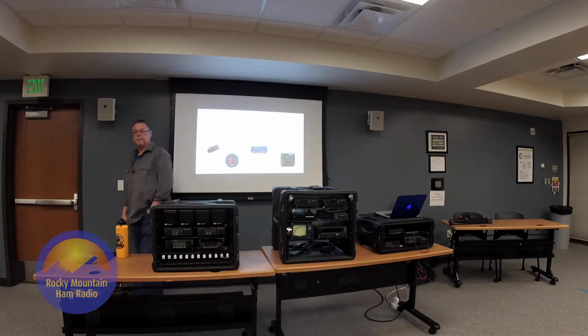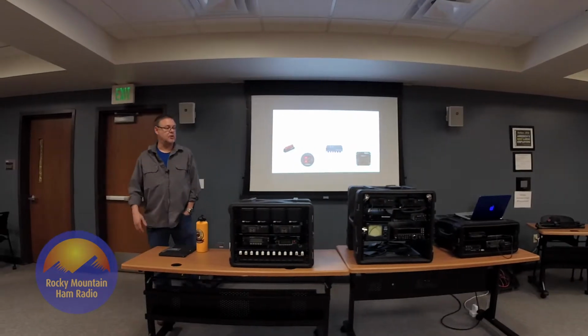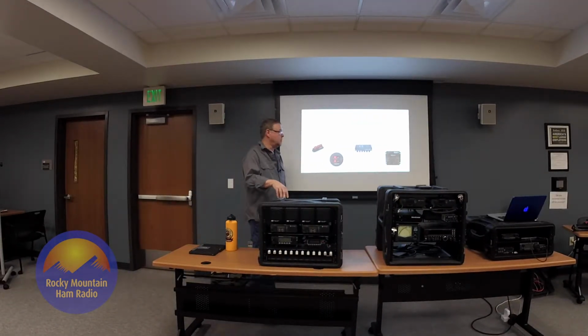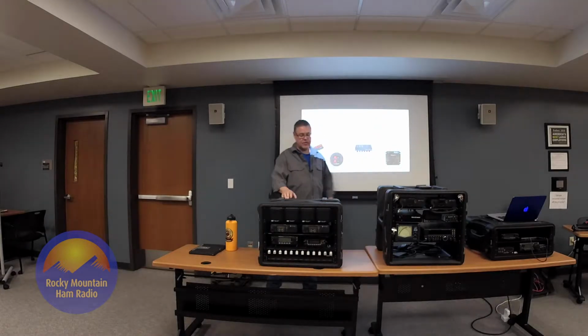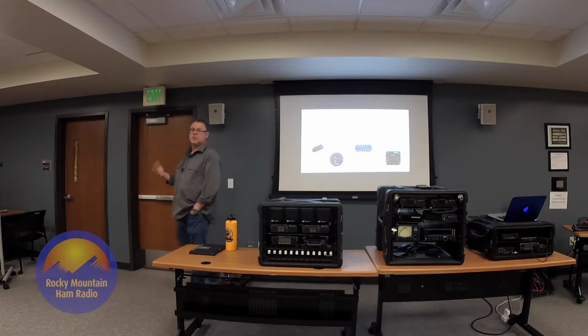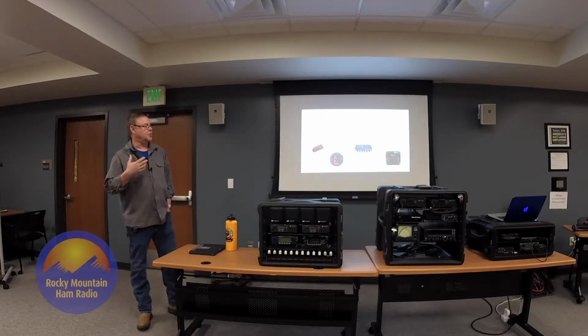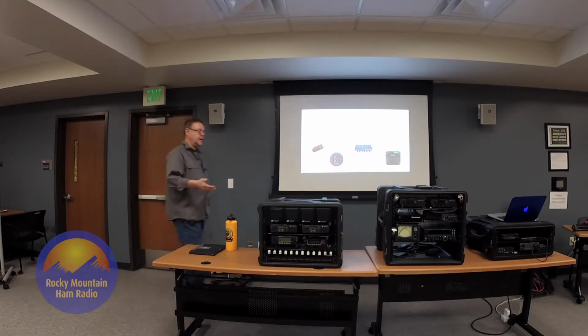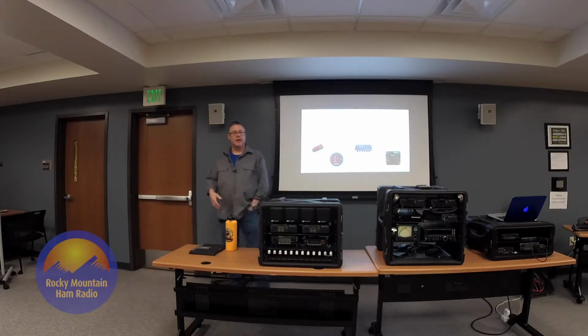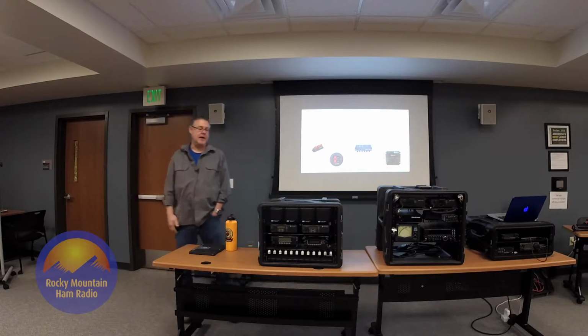If you lose power, your primary source of power in a vehicle, and you have a backup battery or something like that. But anyhow, this one has one of these in it, and what that does, it has a MOSFET switching system in it. And if you lose your primary power, it automatically switches over to my battery backup, my solar power, whatever. When I'm out in the camper or whatever with this thing, I hook it up to solar panels, which feed my main batteries on my camper.